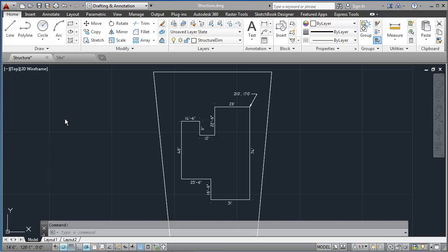The next step in our landscape design is to draw the existing home on the site. An outline of the structure is all the detail needed, as our focus is the landscape features. The polyline, snap, grid, zoom, and pan commands will be helpful in creating the structure and moving around the drawing area. The time, area, and coordinate display tools will be helpful in checking our work.